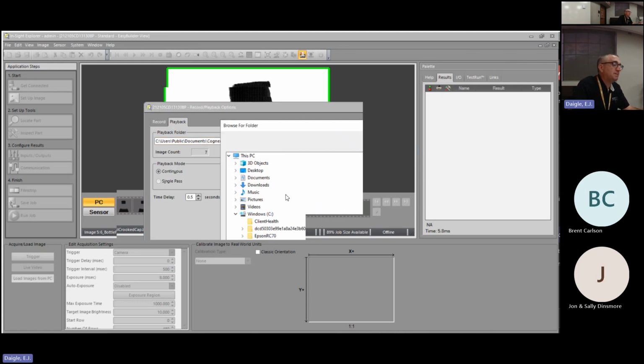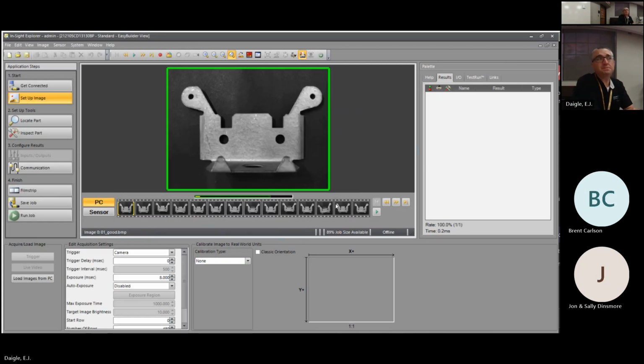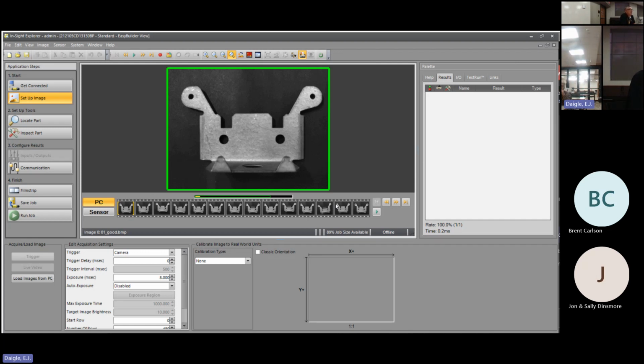All right, I'm going to do one other. I'm not going to spend a lot of time on it because I know we could do vision all night long, and I'd be fine with that, but I don't know that everybody wants to do that. Does that mean a capacitive proximity sensor does not work with metals? It absolutely works with metals. Yeah, so a capacitive proximity sensor is still calibrated on a mild steel target, just like an inductive prox sensor is. But a capacitive prox sensor will measure plastic, it'll measure wood, it'll measure all kinds of things that the inductive prox sensor just can't deal with.